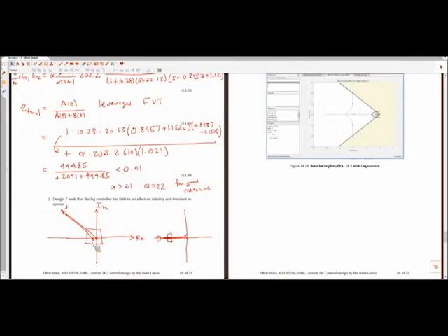And so the way in which you can do that is we're going to put both the pole and the zero very, very close to the origin, and have the zero 22 times as large as the pole. Right? And so now, what do I mean by very, very close? There's no real answer for that. It really depends on the dynamics of the system, right?